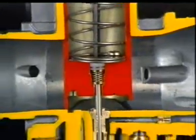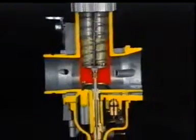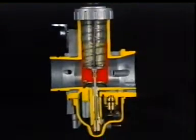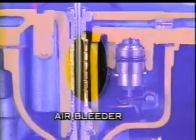The carburetor also involves a number of other elements, and all of these various processes make it possible to supply the ideal fuel-air mixture to the engine to match the current driving conditions. For example, air bleeders are provided in both the main system and the pilot system, at the point where the fuel and air intersect. These air bleeders help to turn the fuel-air mixture into a spray.